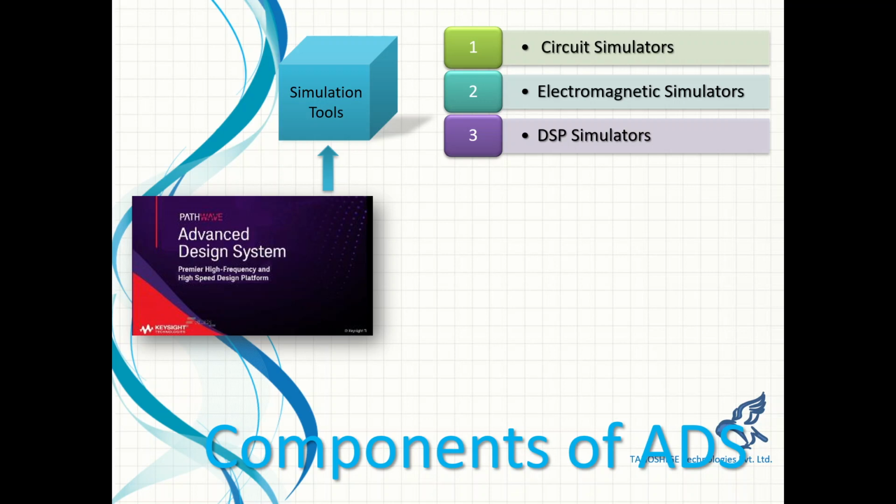So you will be able to do a FEM simulation here. FDTD is in a separate tool like EMPro, but not a part of ADS, but FEM is. So you can do a finite element analysis also, but still the entry tool is going to be 2D, and then the Z profile is provided as a substrate definition. So this is with EM simulations.